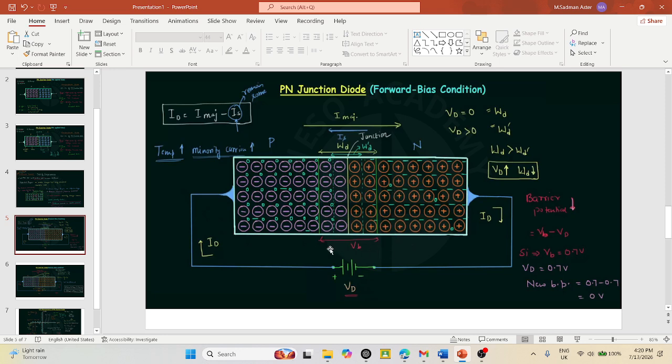If we summarize, when we keep on increasing the external biasing potential in forward bias conditions, the depletion region keeps decreasing, and the potential barrier also keeps decreasing, becoming lower and lower. At one point we overcome the potential barrier and a flood of electrons passes through the p-n junction. Thus, we get current flow through the p-n junction due to majority charge carriers.